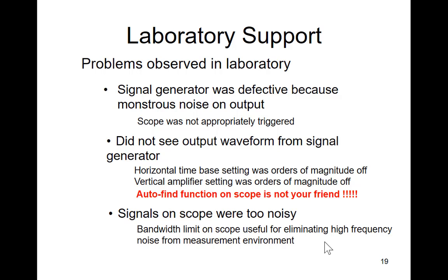Signals on the scope were too noisy. That's a common problem when you're measuring small signals. Take a signal that's in the 10 millivolt range or 50 millivolt range, and it looks real noisy on the scope. It is noisy. We don't have that much resolution on the scope to measure those small signals.